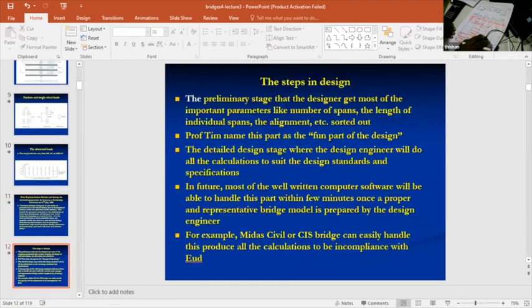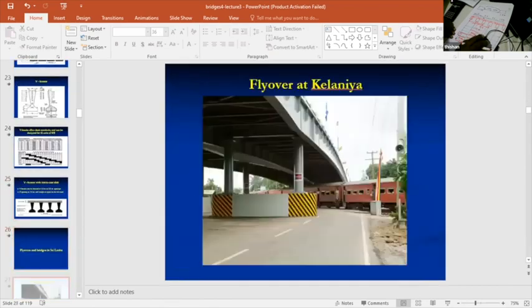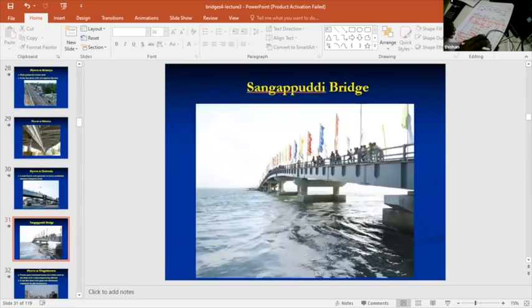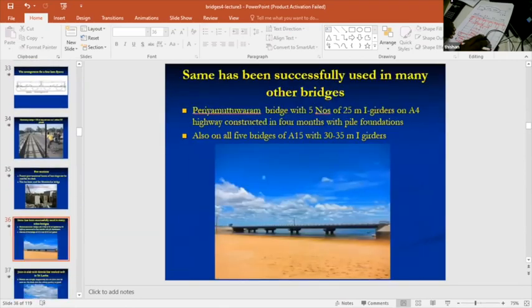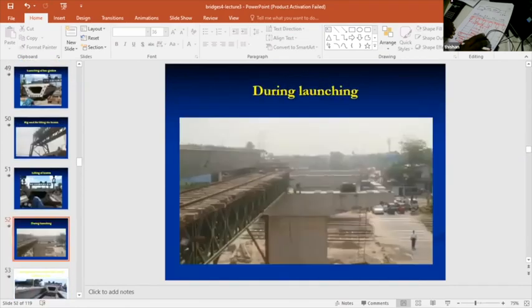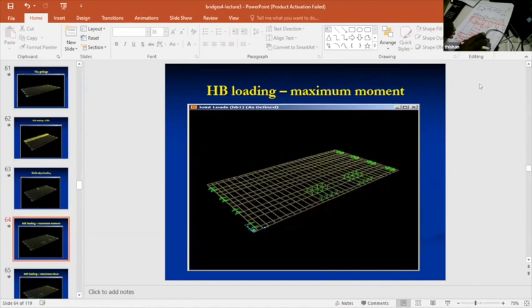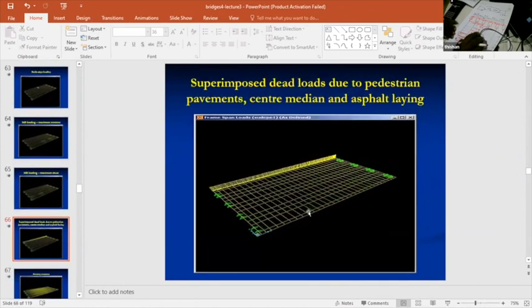And if I want, I can show you some of the simple grillages that we have created. Analyzing a bridge is not extremely complicated. Only thing is you have to look at, now this is a grillage for a particular bridge beam. Once you create these loads, you can either apply it as a transverse load or a line load.